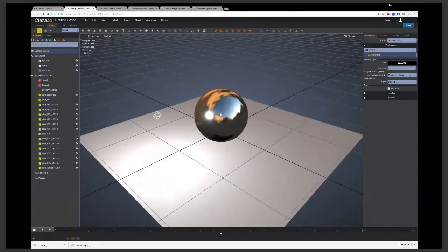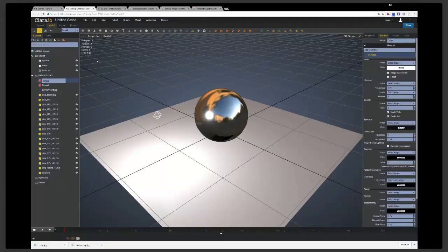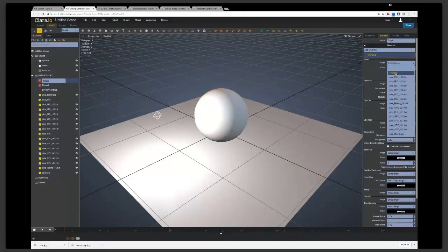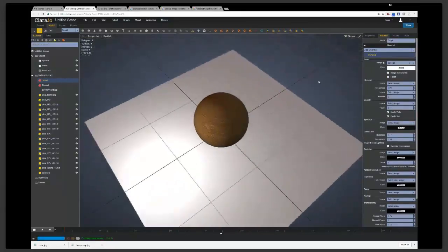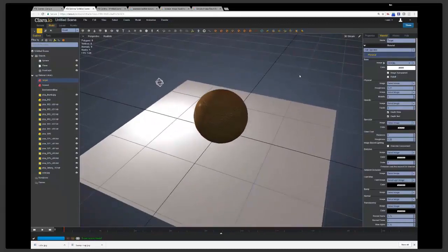So once you've got the textures you want to set up, usually what you do when you want to set up a specific material is you find the surface variant color. That's your base map. So let's put that on here. This is the color of the leather that we brought in, that we found through Google. And once we have that, it's a simple matter. We can go to our target object, or the target material, and I'm going to get rid of the metallicness because leather is not metallic. And you just set that into your base image here. So we pull in our color. And there we go. So we have a leather object.